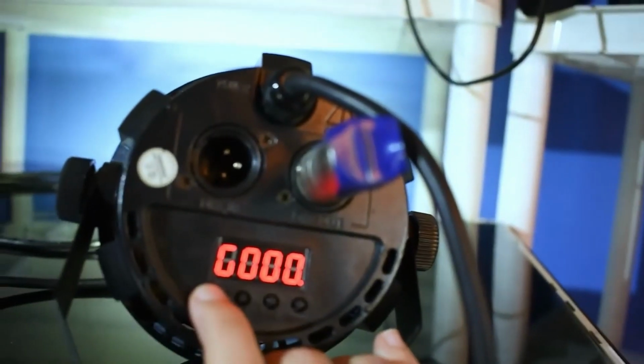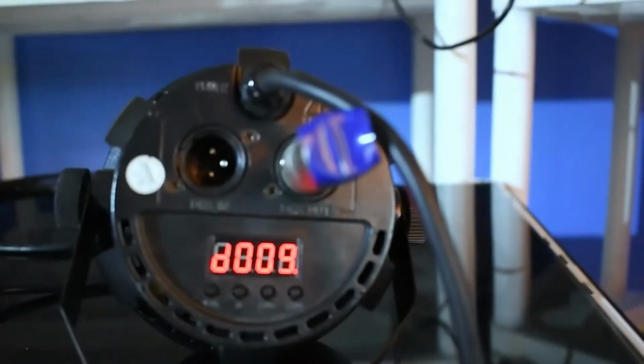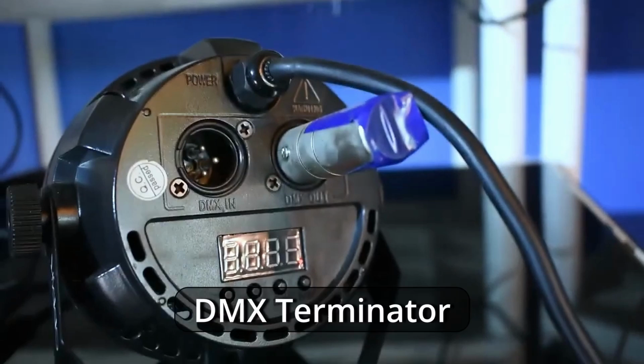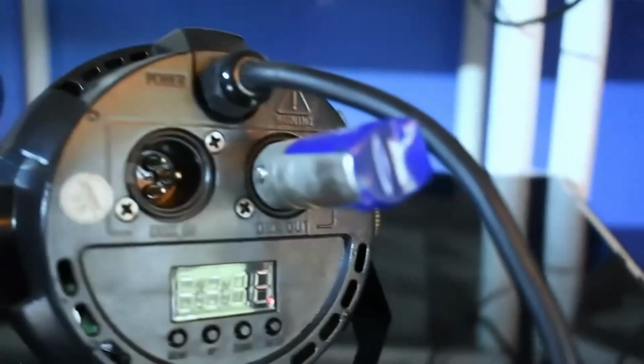We'll see that when we get a D. Okay. All right, and this one is already set to DMX channel 9. You'll notice that I have a little widget thing sticking out of the output of this light. That is a DMX terminator. You're going to need a DMX terminator on the output of the last light in your daisy chain. Okay, now that my 2 lights are properly addressed, now I can interconnect them.